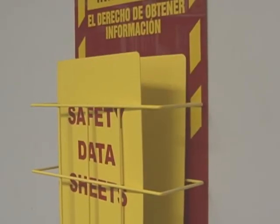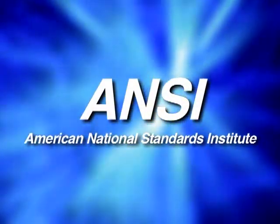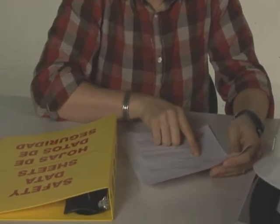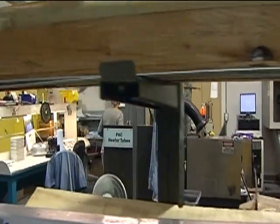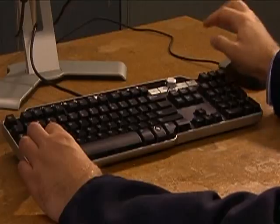This format is the same as the American National Standards Institute standard on safety data sheets, which is familiar to many U.S. employers. This uniform approach to SDSs improves its effectiveness, makes it easier for your employer to comply with the regulation, and provides a safer workplace for employees. Employers must maintain copies of the SDSs for each hazardous chemical and must ensure they are readily accessible during each work shift to employees in the work area.